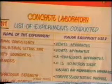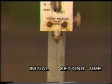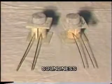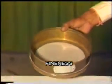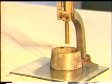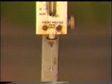To assess the quality of cement, the important tests conducted in the laboratory are normal consistency, initial and final setting time, soundness, compressive strength, and fineness. In this film, the determination of normal consistency and initial and final setting times shall be dealt with.